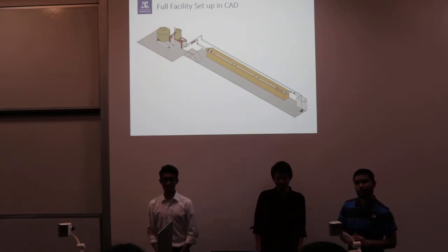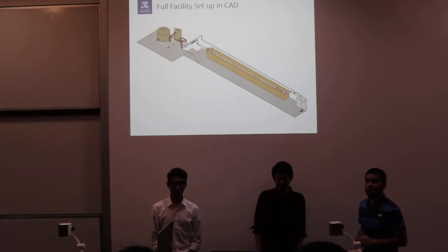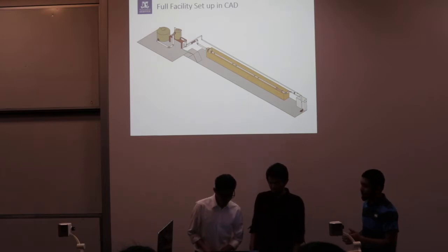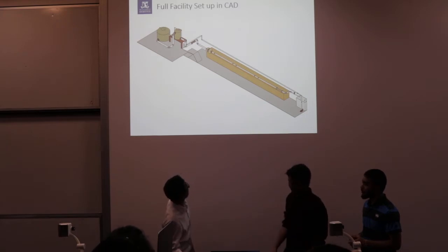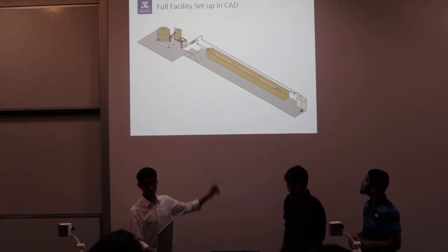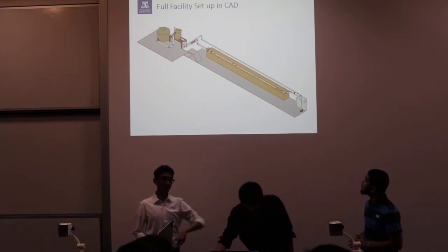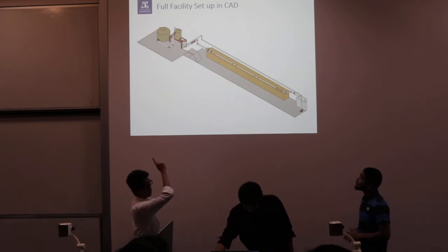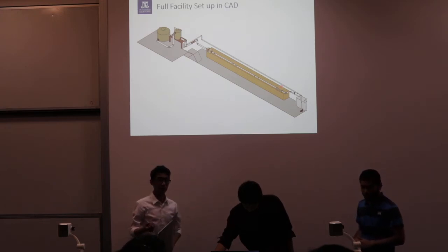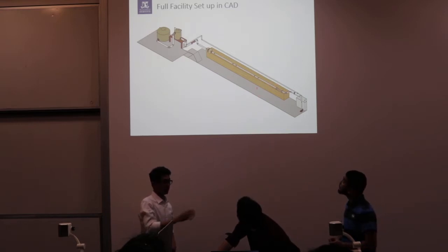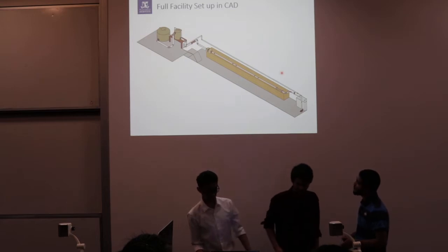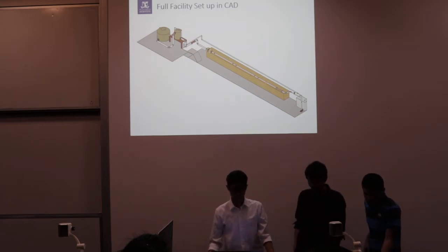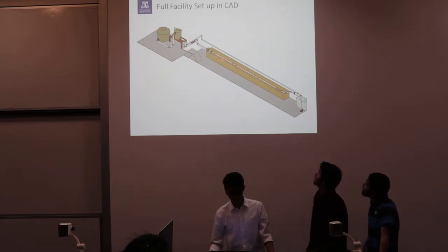In this design, where is the measurement system again? Okay, so the measurement system is going to be at the end, but we're going to have pressure taps along all of the pipes. Basically we're going to measure pressure at every 1 meter. So we're going to have one pressure tap here, and then one every 1 meter.